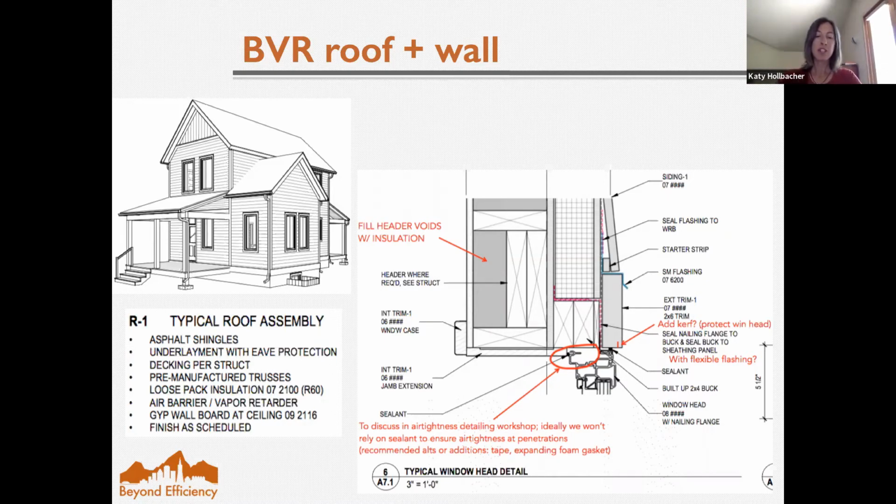So the question is, it's concern about having a home that's too tight or a building that's too tight. So every building needs ample ventilation, that's a given. The question is, are you hoping you're going to get that ventilation through random air leakage, or are you going to deliberately provide it with mechanical systems? And the problem with hoping you're going to get enough ventilation through just leaks is that you have no control over it. Depending on the temperature differential, how hard the wind is blowing, just the design of a building, you could get way more air infiltration than you need on a certain day, or get a fraction of what you need. So you have no control. So that's why, again, the best practice is build tight, ventilate right.